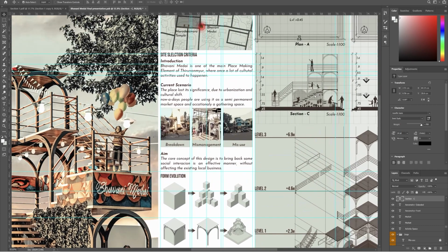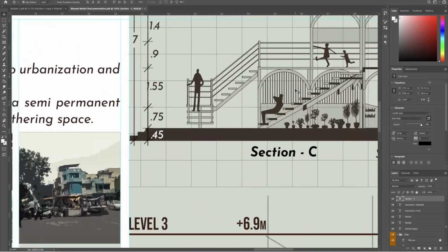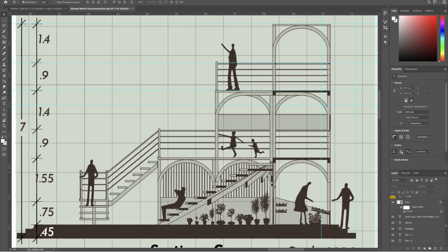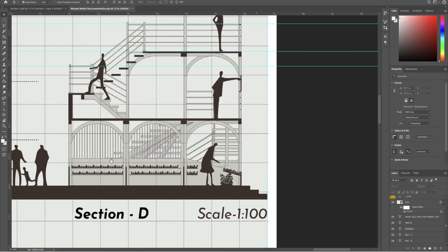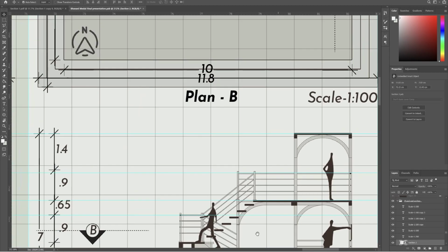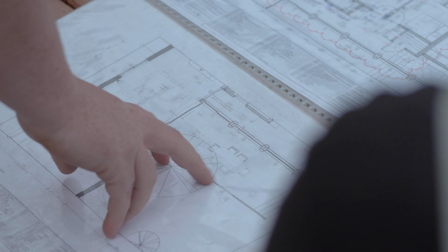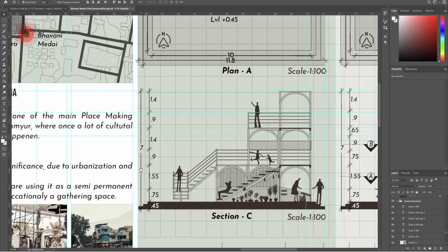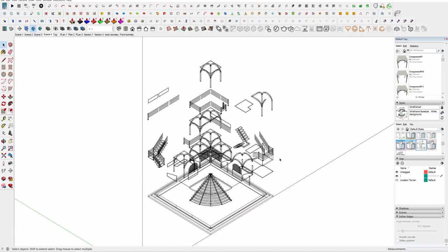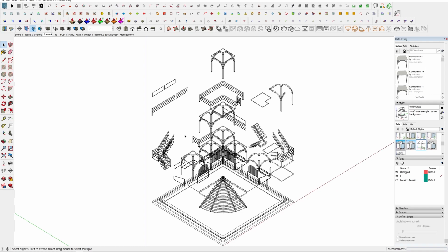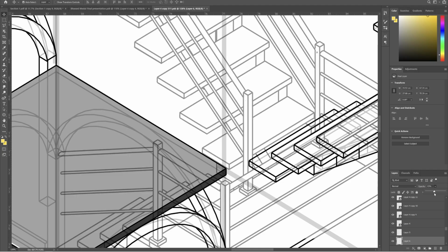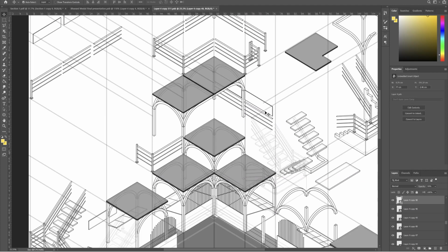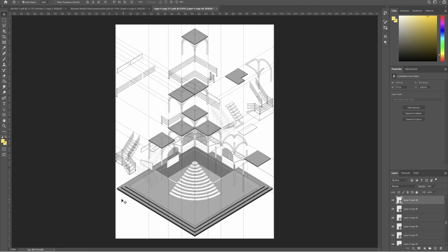I advise to use a solid hatch and 1 or 2 line weights, not more than that, because usually they don't expect any detailed drawings in a closed jury. Most of the competition briefs expect just a conceptual drawing because the jurors ain't got time to surf through all your details. Also, you can play with different types of techniques. For instance, you can show your wireframes like an X-ray vision by taking a wireframe style and reducing its opacity. You can also introduce a bunch of guidelines and stuff. Sky's the limit, you can explore your own creative ways.